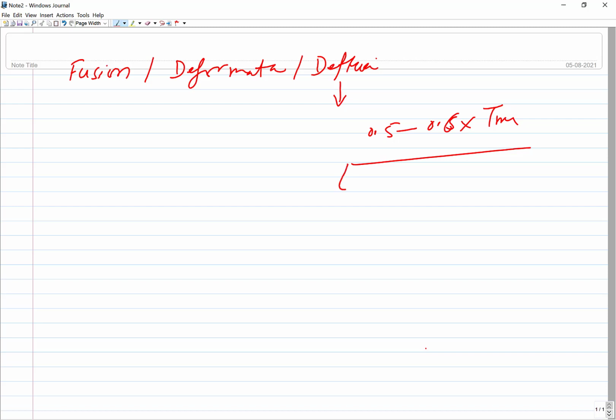Okay, so there are certain problems here. Let us talk about the joint first. Since the process is entirely based on diffusion across the interface, the diffusion of atoms from metal A to the other member, A or B, can take place. The diffusion of atoms from one side to another is crucial for development of the bond at the interface. So you need to develop suitable conditions for atomic diffusion to take place.